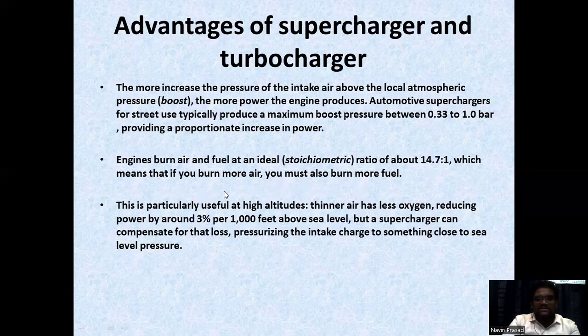This is particularly useful at high altitudes. Thinner air has less oxygen, reducing power by around 3% per 1,000 feet above sea level. But supercharging can compensate for that loss, pressurizing the intake charge to something close to the sea level pressure.